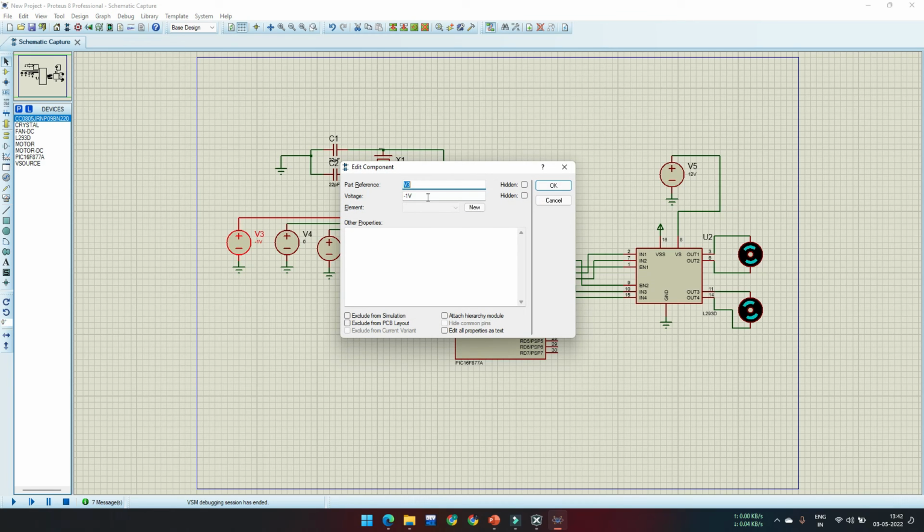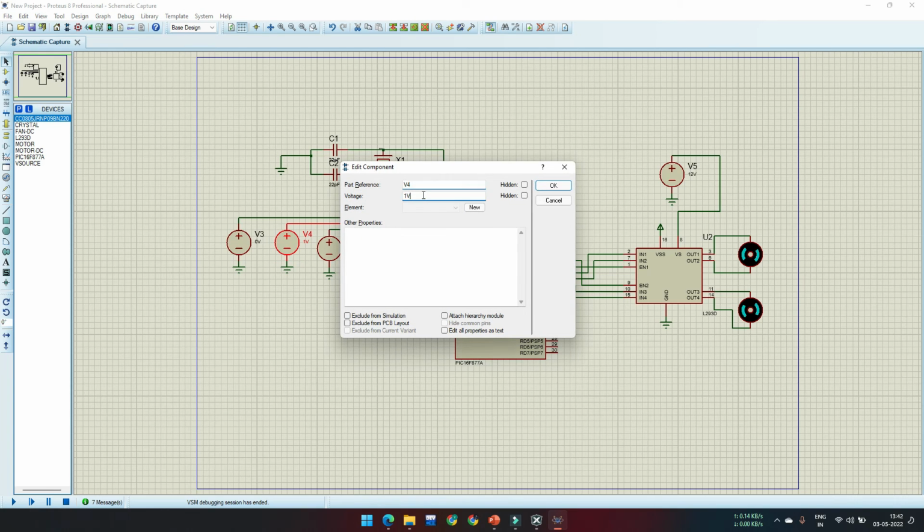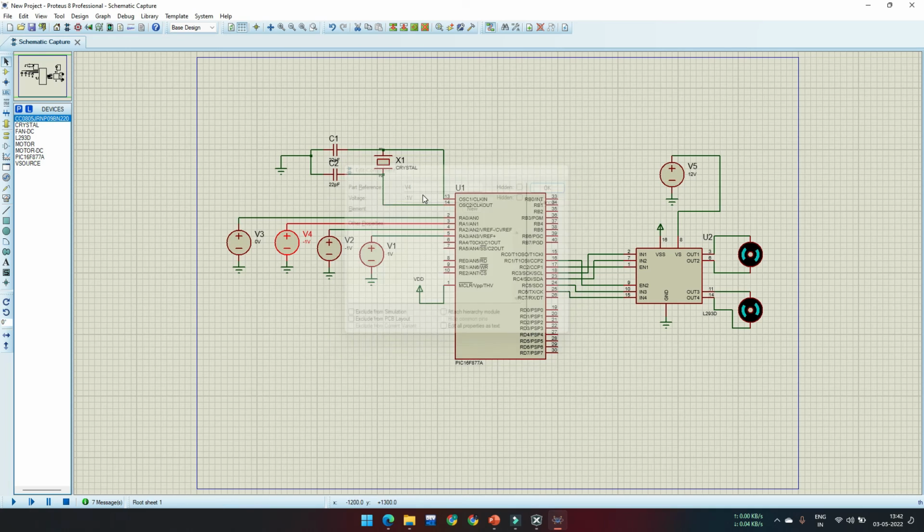If we want the vehicle to turn around its axis, then we can command 0 linear velocity and the angular velocity as maximum. And now we can see the motors move in opposite directions so that the turning can take place. If we want to turn in the reverse direction, then we can command negative velocity as angular velocity, and then the motors will again turn in opposite directions to each other and the turning would be opposite to the previous case.